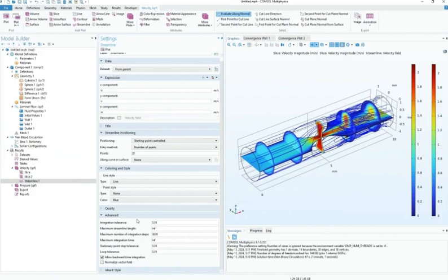And we can even have specific points if that's something that we want. So over here, we can see streamline positioning. Right now, we have 20 points. We can change it to 55 points, and then go over here in the plot option. We can see now that the streamline is much more complex. We have a much more detailed representation.